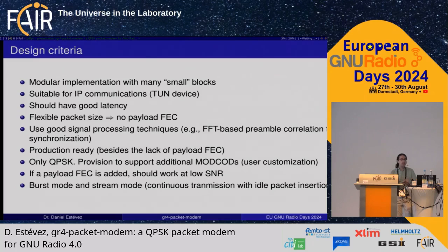Because I wanted to test latency at any different packet size, and that unfortunately means there is no FEC for the payload, because if you define an FEC which is good, I don't know, an LDPC code, then it pretty much ties you to one particular packet size or set of packet sizes. So there is no payload FEC, but there is the provision. If the user wants a fixed packet size and his own FEC algorithm, there's a place to put it.